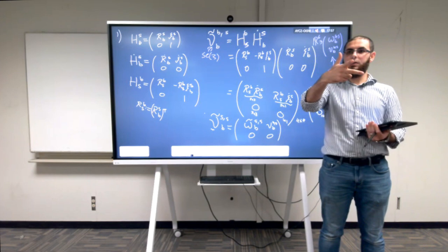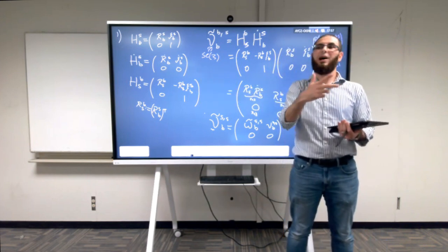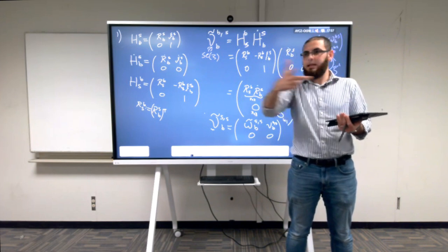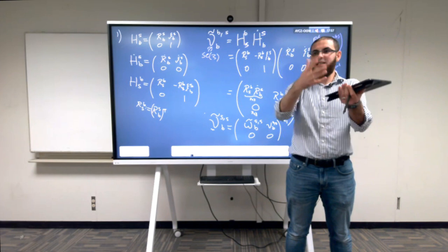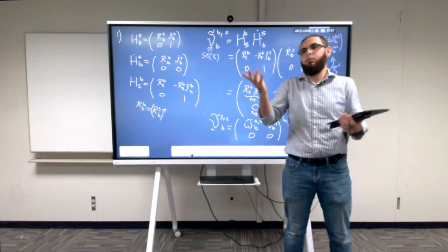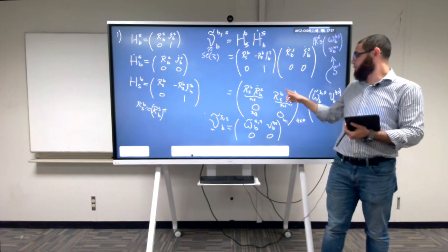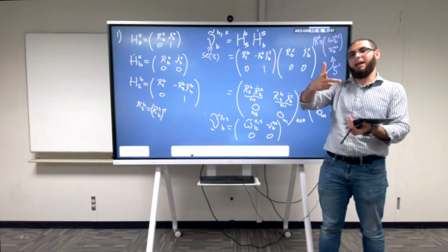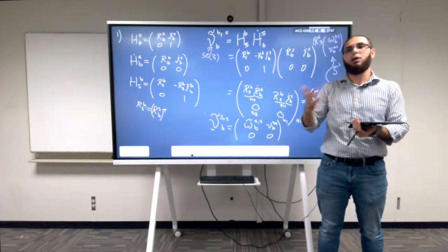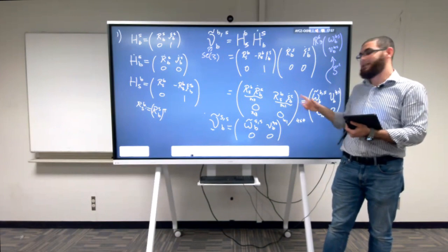This means that the rigid body moving from this point to that point is not rotating. So it is as if it's acting as a point mass, right? If you have a rigid body that's not rotating, then it's as if it's a point mass. So this is what this says. Then when you take the rate of change of S with respect to B for all time, you're going to find it's zero. It doesn't have any angular velocity, but it has some linear velocity. So you just go back to the case of a point mass. Okay? And the same also here.